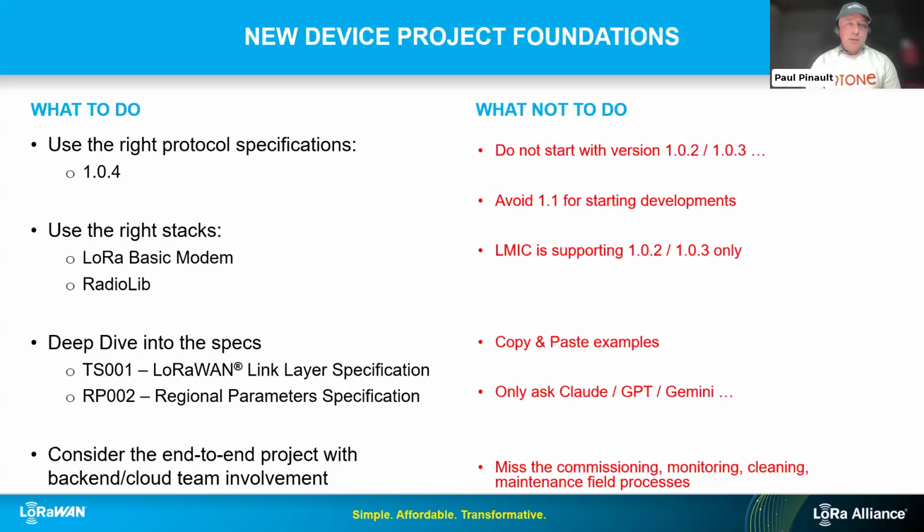To implement the stack, you won't develop LoRaWAN from scratch for sure. What is important is to use a library that is certified for your development, and there are at least 2 libraries that are really common. The first one is the LoRa Basics Modem. I would say that it is a reference implementation of the protocol, and you also have RadioLib, which is more and more used in this area.